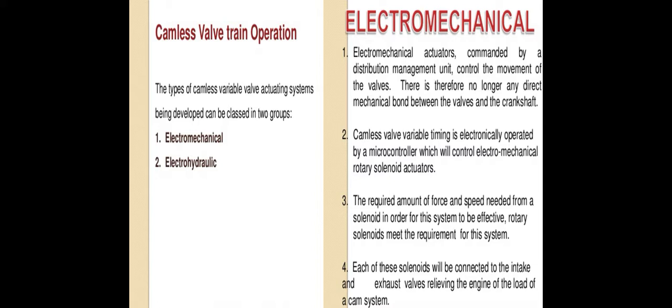Camless variable valve timing is electronically operated by a microcontroller which controls electromechanical rotary solenoid actuators. Given the requirement of force and speed needed from a solenoid in order for this system to be effective, rotary solenoids meet the requirement for this system.